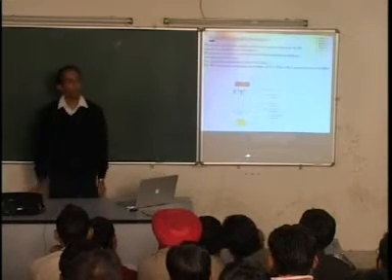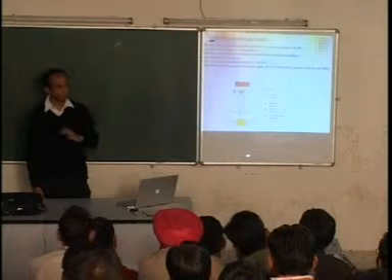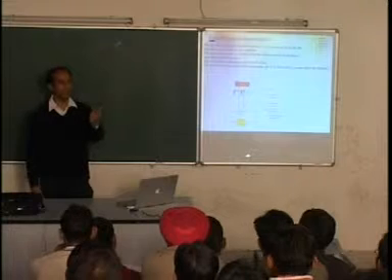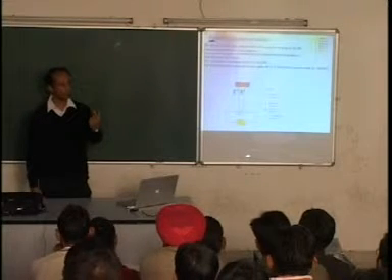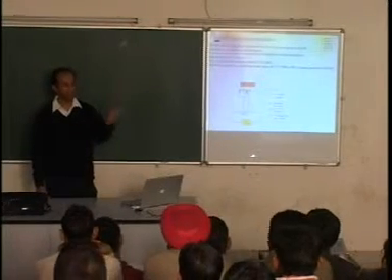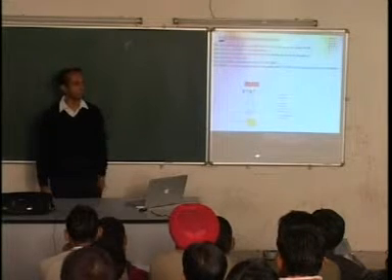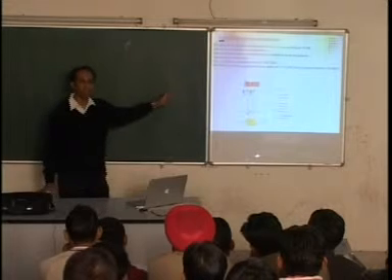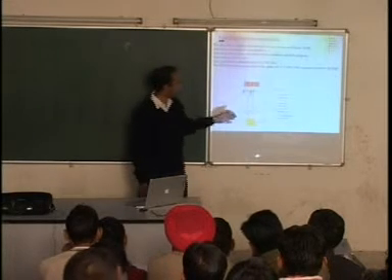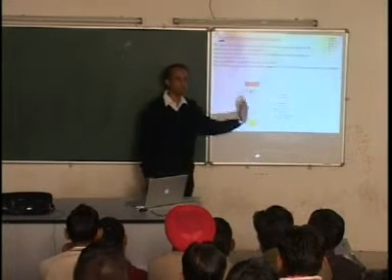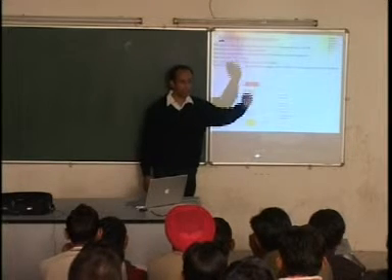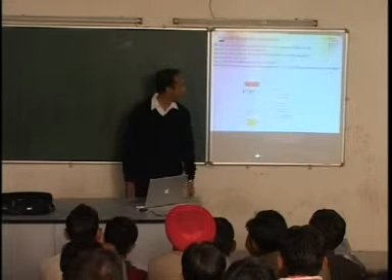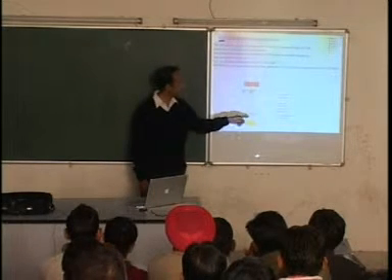Those are here inside that red bias circuit box. Okay? So the modification is that we don't let our resistors, you have seen resistors, they are big components, they don't work at microwaves. We don't let our resistors come into contact with a microwave circuit. We space them out with some kind of filter, so that our useful RF signal does not go into those resistors. And microwave signals, that's not a resistor, that may be an antenna for all you know. Okay? And here's the rest of this.